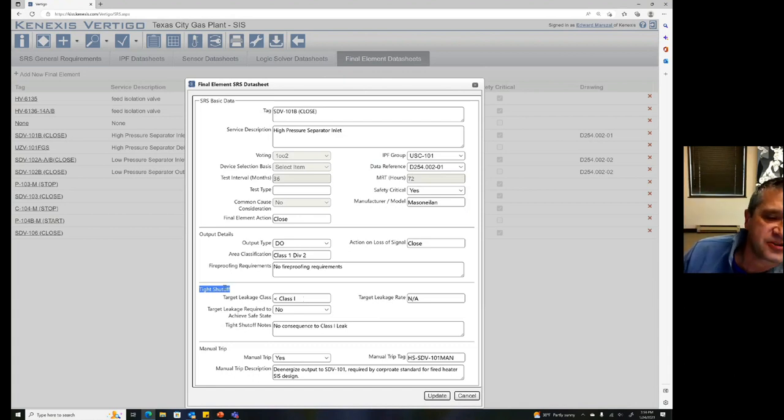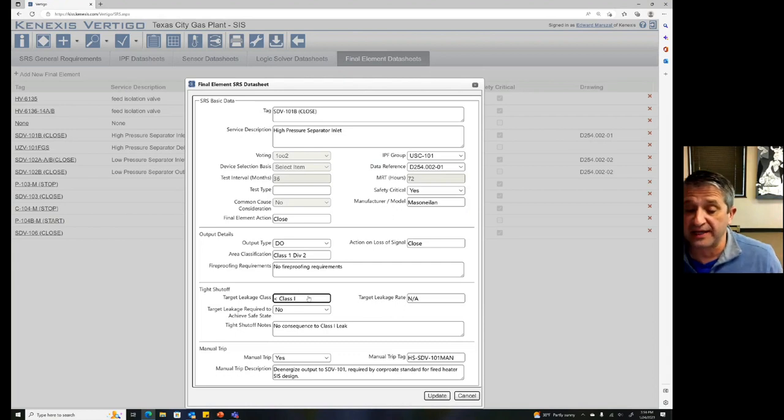Okay, so for each one of the valves, we give you an option to say what is the target leakage class or what is the target leakage rate. I would recommend you just use target leakage class instead of leakage rate, but you know, to each his own.